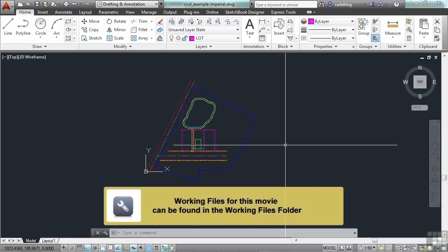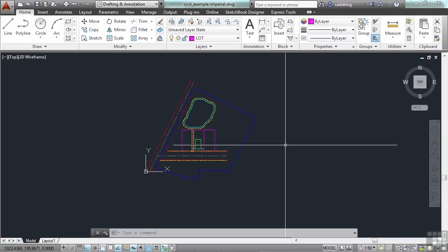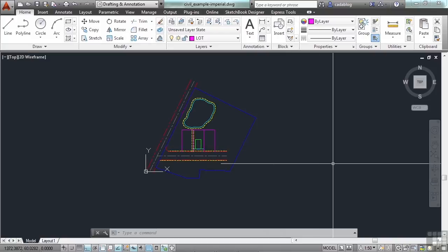By default, AutoCAD sets up the UCS in a world coordinate system. That means that the origin is at coordinates 0, 0, 0, a 0 for each axis. In AutoCAD LT, there are only two, X and Y. So it sets up the origin at those coordinates of 0, 0, and angles facing east, or to the right of your screen, start at 0 degrees.